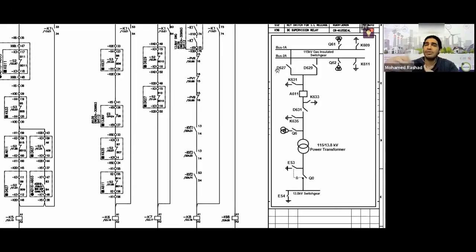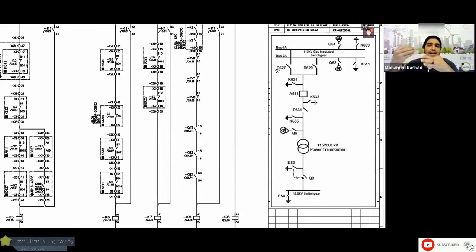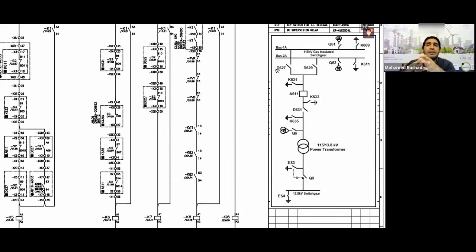The other thing we mentioned is that as a result of this scheme being used in size, meaning it is inside a tube within gas, of course, you cannot handle it. You will install a breaker. As a person, you cannot do a rack in or rack out, meaning the breaker is not withdrawable. You will install a breaker and the breaker will be fixed. That's why I want to isolate the breaker from the bus side and the line side so I can integrate it into the system. That was the second purpose of using the disconnector switch. Beautiful articulation, beautiful.